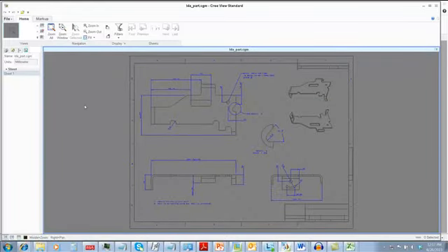When importing data from legacy CAD systems, we can import the 3D models in many ways, such as STEP, direct translators, full feature migration methods, or simply reauthoring from scratch if you don't have a 3D model to start with. On the other hand, the 2D drawings can be imported by using IGES or DXF translations.